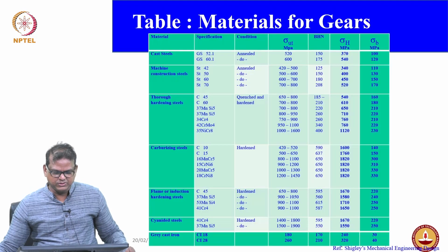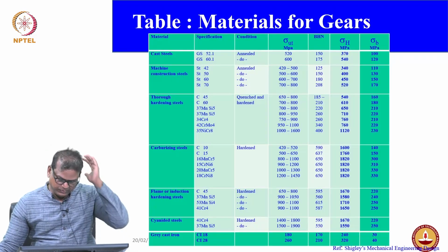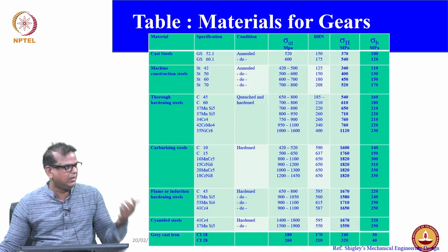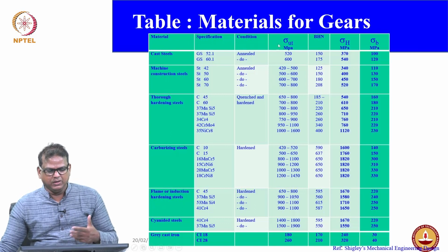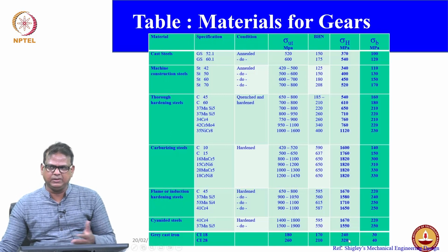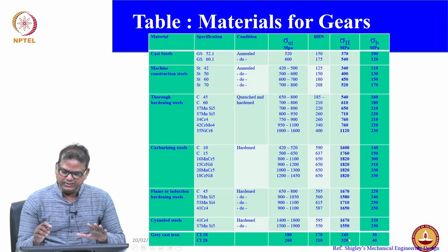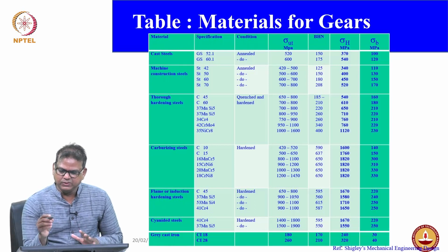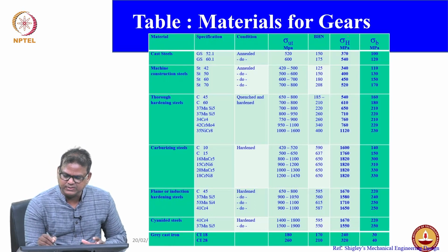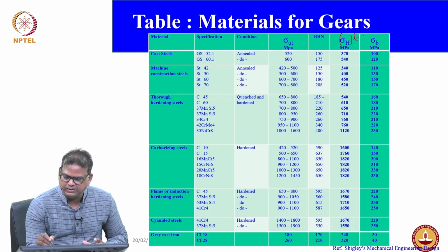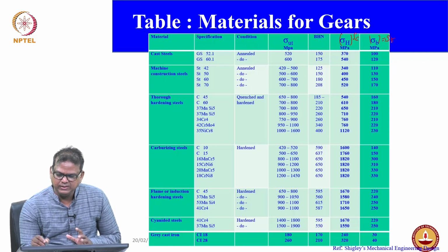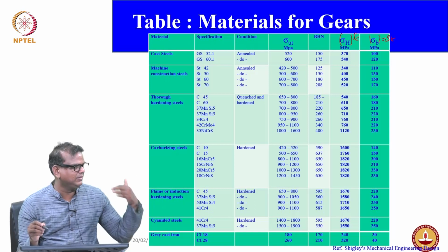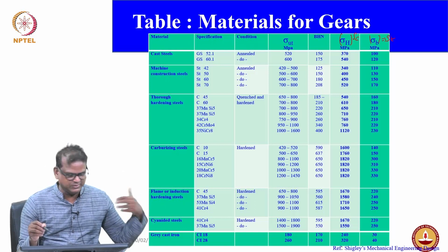Right. Now, I will show the actual materials. Either the hardness or the grade is given and you have to choose the material, that is one way. Otherwise, you can choose from this table and move on. I think I have already explained this table. This is not sigma H, I would say SC, and this is sigma, nothing but ST. Always ST is 3 times lesser than SC.